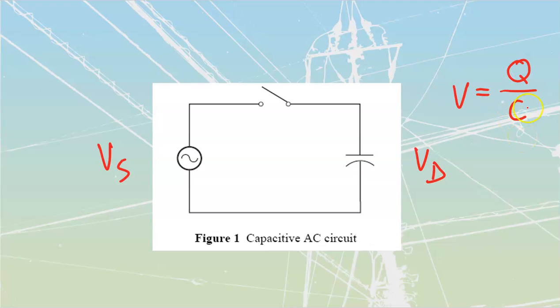In other words, my capacitance, that's going to be a physical build, 8.85 times 10 to the negative 12 times K times A over top of my little d. All of that is going to define physically how a capacitor is built. But Q is the finite number of electrons that have accumulated on it.